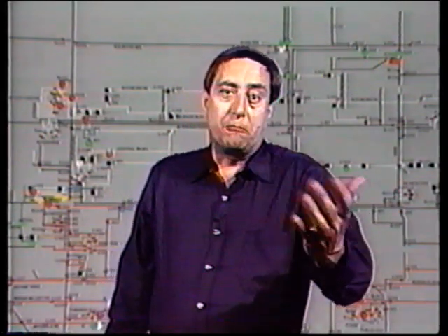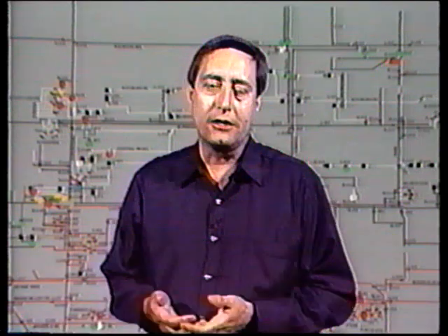This relay is highly sensitive and will trip in about 16 milliseconds, that is 1 cycle, so providing high-speed operation. In spite of these apparent advantages, this system is still not in wide use throughout the power industry. One problem is that it cannot use the conventional CTs, which are commonly purchased and stocked in large number for any utility company. Moreover, the linear couplers cannot be used for any other application within the system.